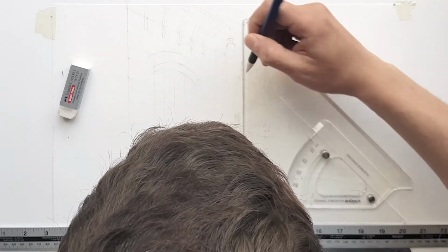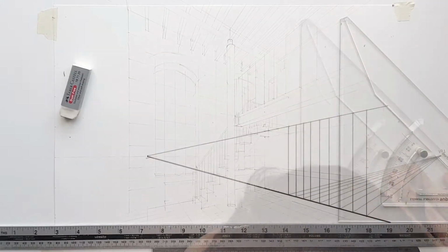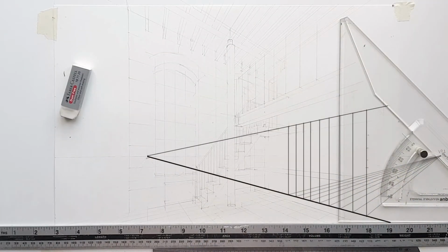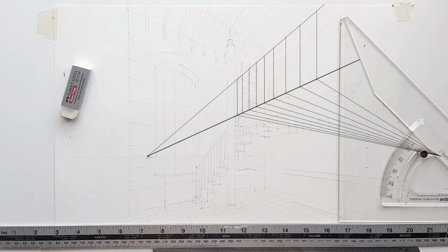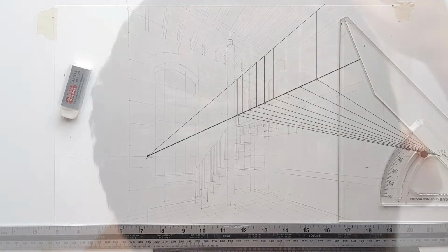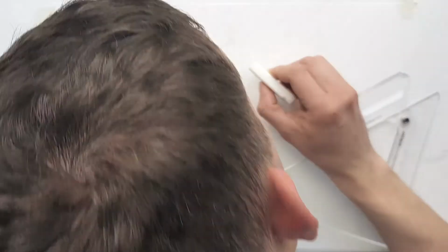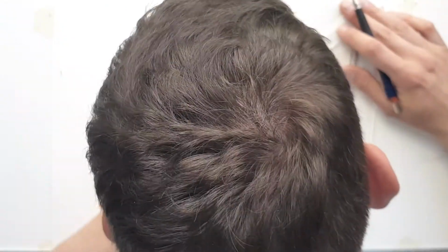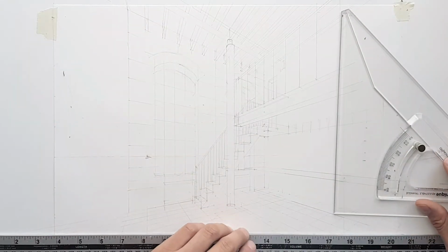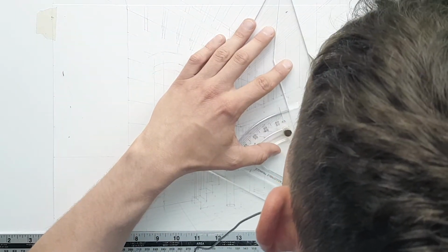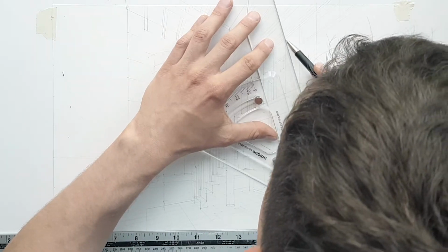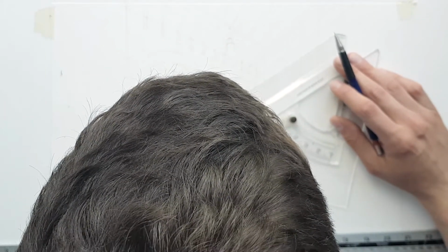The railing is then projected up, and at the moment at 0.5 meter between each railing, that's a bit too much. The openings are too big. Realistically, somebody can fall through, so I am dividing the gaps using cross methods once more to have more realistic gaps between them.